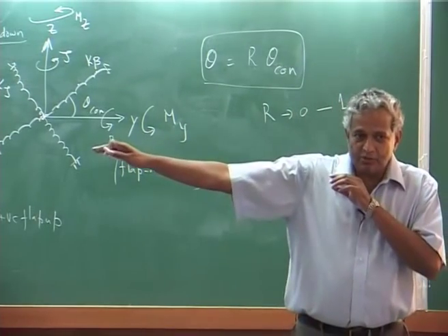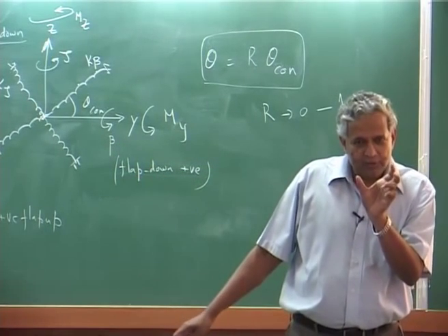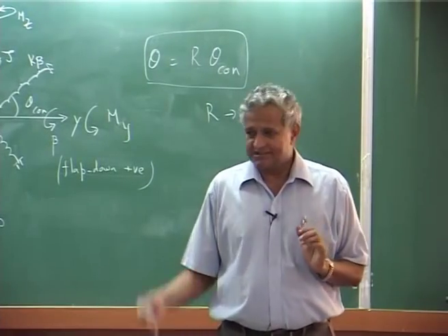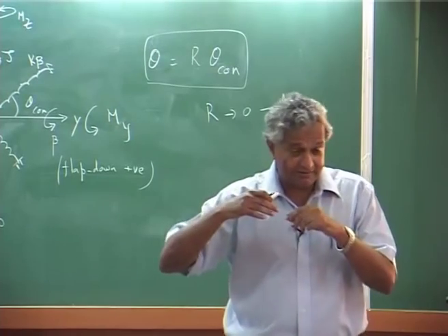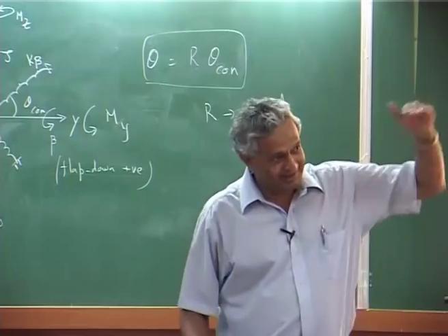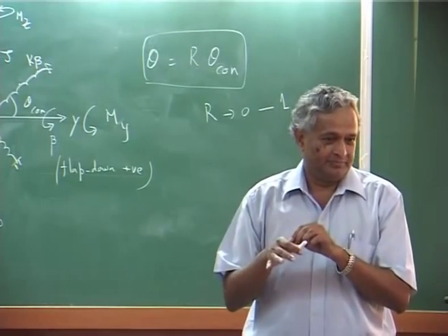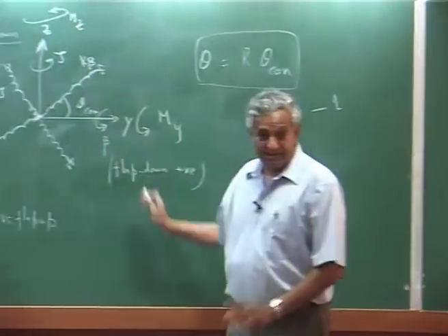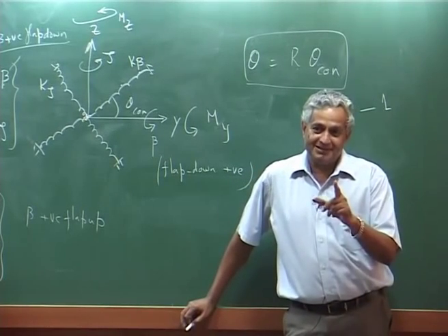See, the blade is not going to bend, you are putting at some place where you deliberately make it a little soft. Yesterday he was mentioning that. So that you create flexing, but the stress and strain levels are below the limit, but still it is flexing. Okay. At that location you make these two stiffnesses the same, then you can eliminate the flap lag coupling.